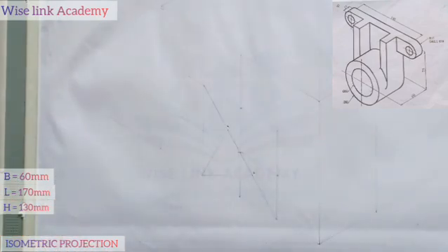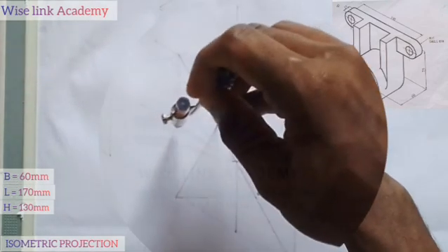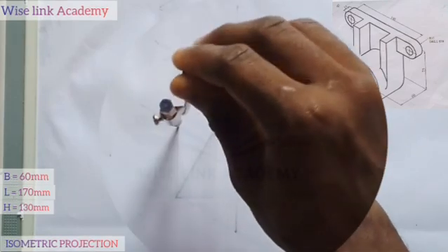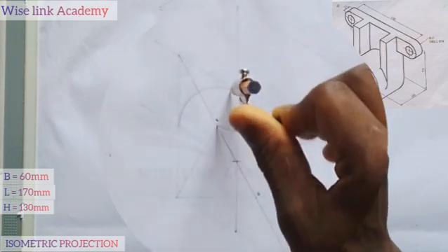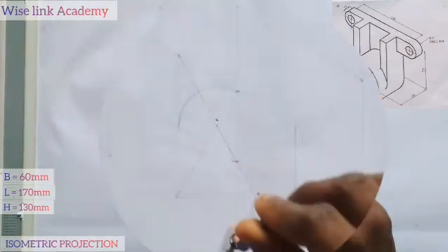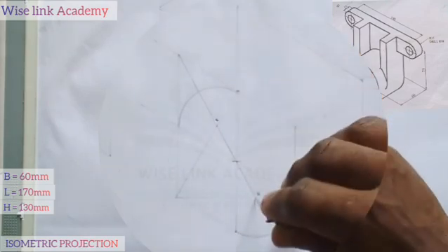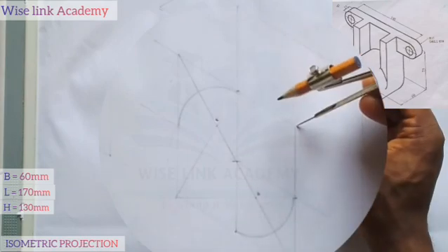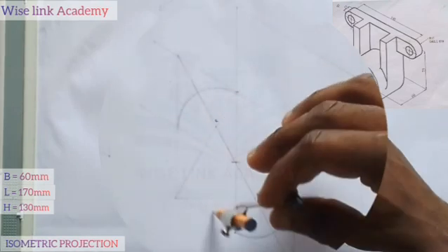Alright, at that point I will take my compass at this point here, point B. So now I'll strike an arc to produce that isometric circle this way. I have this. Next up, at this point here, I'll take it the same way to produce my isometric circle, right? So I have this. Next task, come to this edge point, extend it this way to produce the isometric circle,